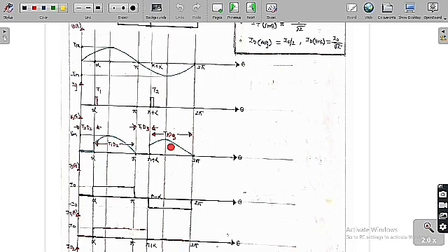If we apply KCL, in this region we get Is of t equal to minus I naught of t, so it is minus I naught. Therefore this is the value we are going to get. Whereas from 0 to alpha, T1 is still in forward blocking mode.